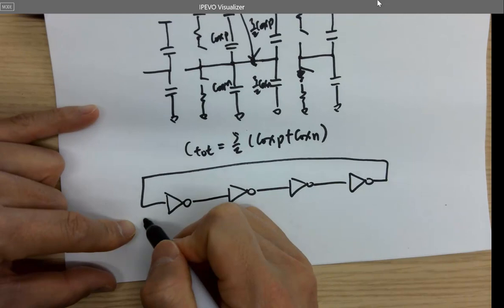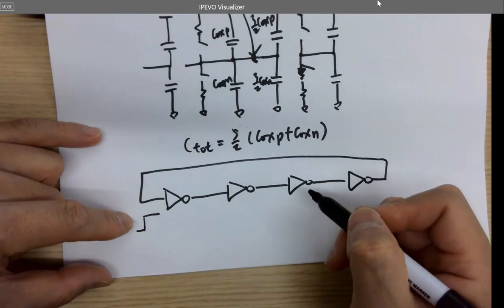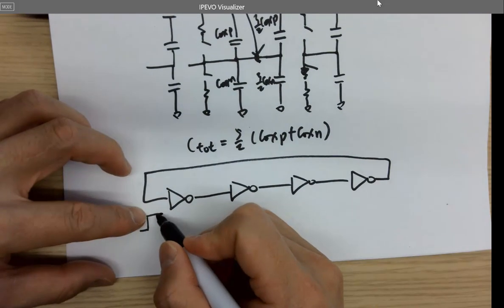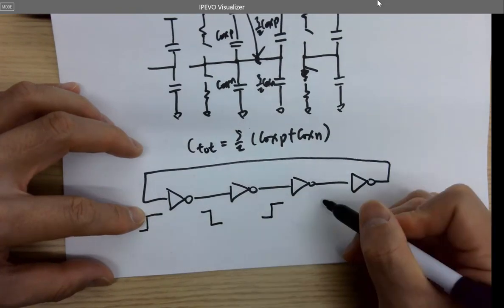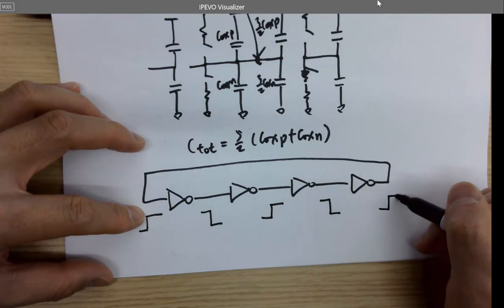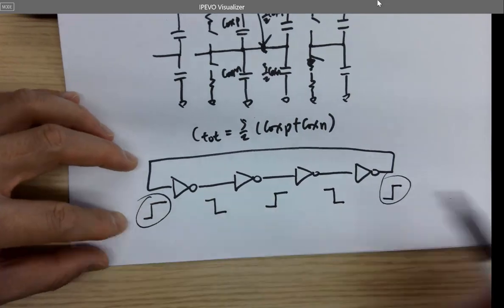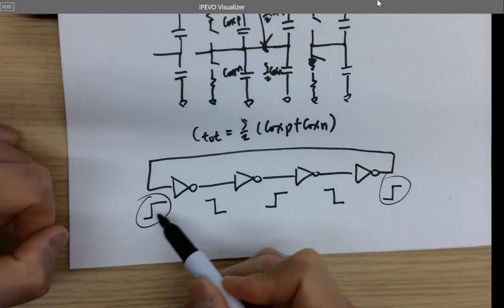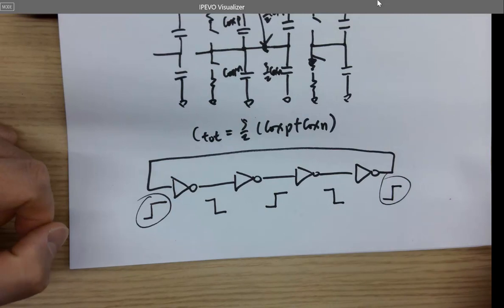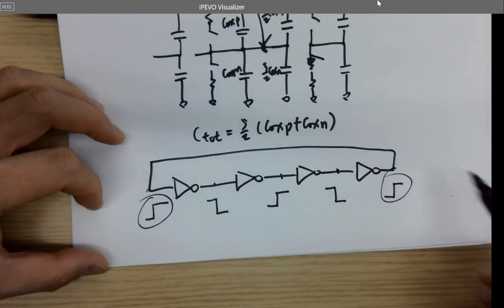Why? If you have at the moment a voltage, for example, from low to high, so it becomes a logic 1, logic high. It's being inverted, inverted, inverted, inverted. Still the same signal. It's not changing the shape. Still itself. So it's not going to oscillate. All the signals at each node are very stable. So it performs like a latch.